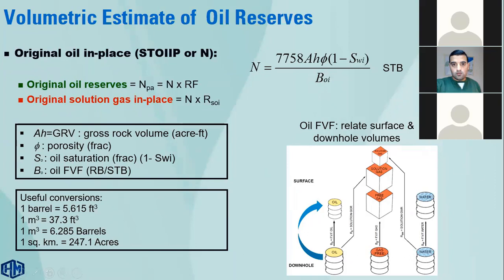Simply, the initial oil formation volume factor term is used to convert the downhole volumes to equivalent surface volumes, because the volume of oil, for example, will be reduced from the reservoir or downhole to surface due to mass losses, because more solution gas will be released while we have a reduction in flowing pressure from the bottom of the well to the wellhead.